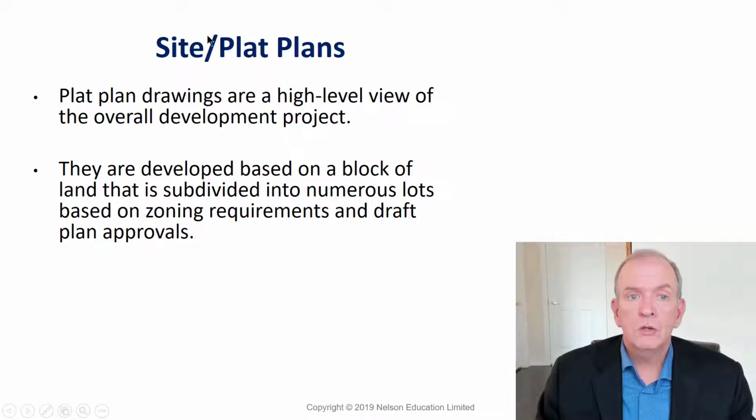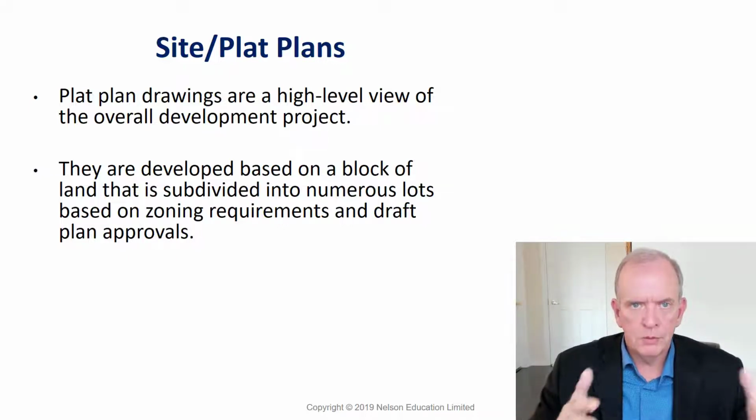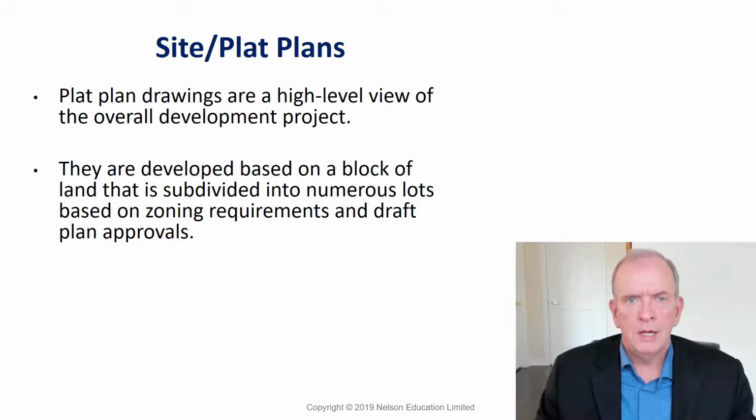You may also hear the term plot plan used. It's typically more of an American term. I see it used out west as well. Site plan, plot plan, they mean the same thing. So it's just that individual property, and what are the parameters around that property, and what are we going to build on it, where are the setbacks going to be, and what are some of the restrictions that are involved with that.